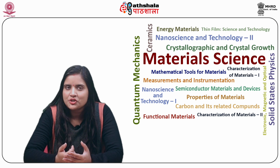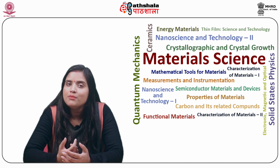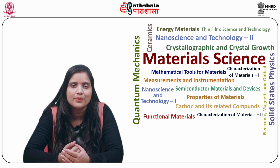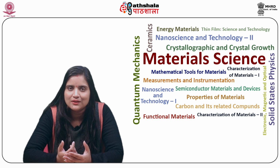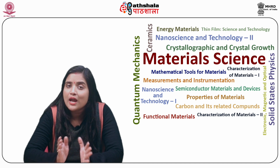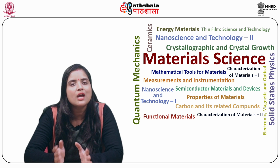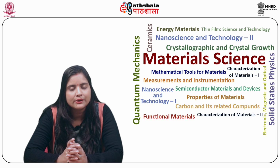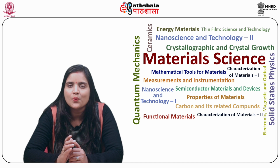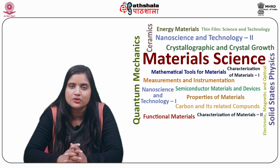Another application is medium phosphorus, which is bright and high speed. Medium phosphorus electroless nickel plated steel parts give performance similar to stainless steel. There is no buildup of electroless nickel on edges or ends, and it covers both inside and outside uniformly. The hardness can be increased from 45 to 68 Rockwell C by applying some sort of heat treatment.